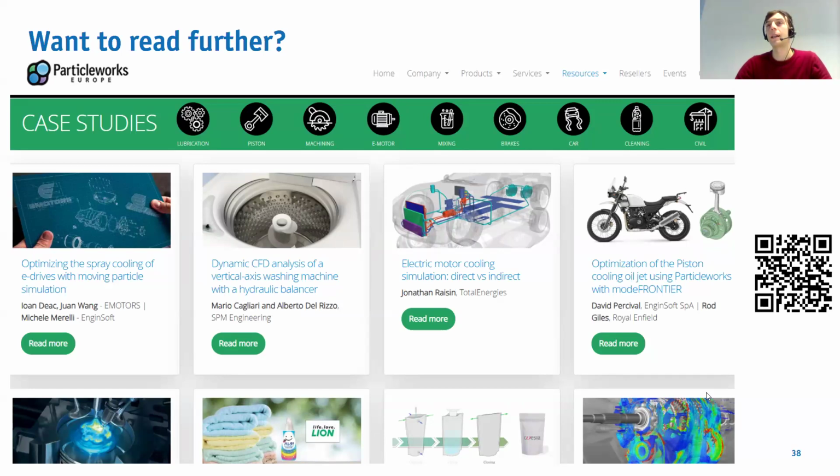Diego asks if we can set equations in the program, for instance, variable specific heat or non-Newtonian fluid. Yes, there are several ways to customize both heat transfer coefficient or non-Newtonian fluid laws. We can have user-defined functions there, also in the rotations or in the acceleration profile applied to the system. So the short answer is yes.